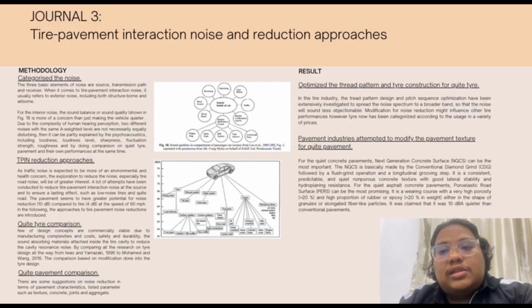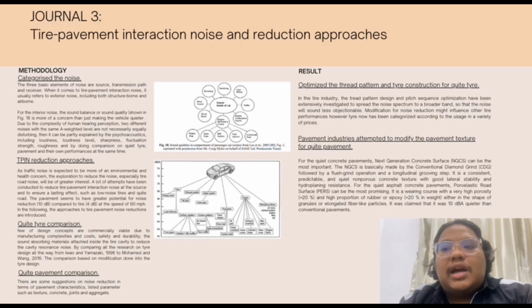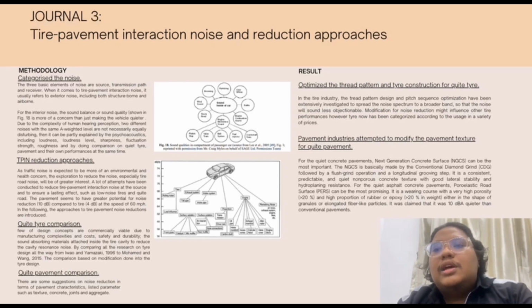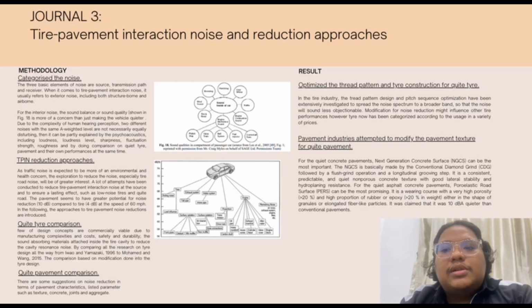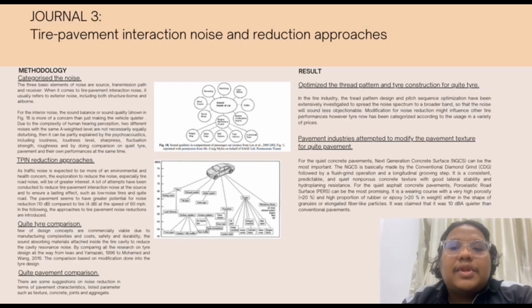In the tire industry, tread pattern design and pitch sequence optimization have been extensively investigated to spread the spectrum to a broader band, so that the noise will sound less objectionable. Modification for noise might influence other tire performance. However, the tire now has been categorized according to the usage in a variety of prices.